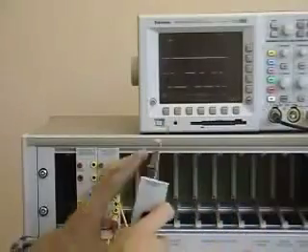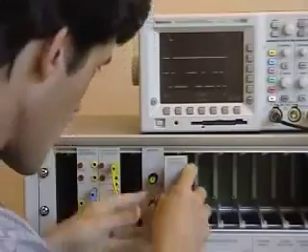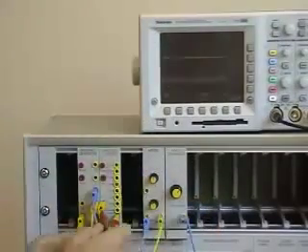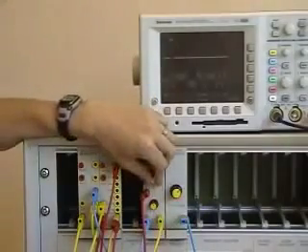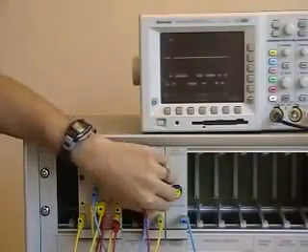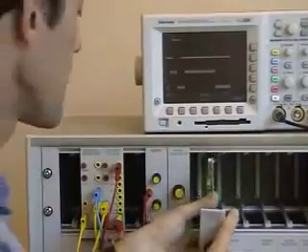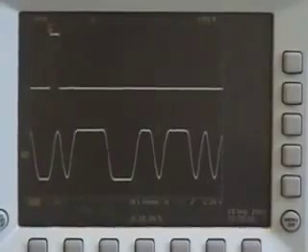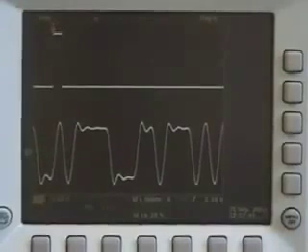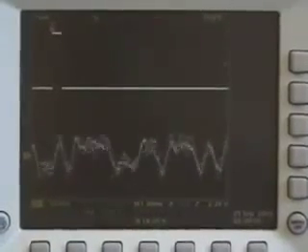We start building the channel with an adder block, and a noise module to add noise in the channel, patching the transmitted signal into the channel and then adjusting the signal gains to the desired signal-to-noise ratio. Band limit the channel with a filter block of various switchable phase and frequency responses. And you can vary the level of band-limited noise.